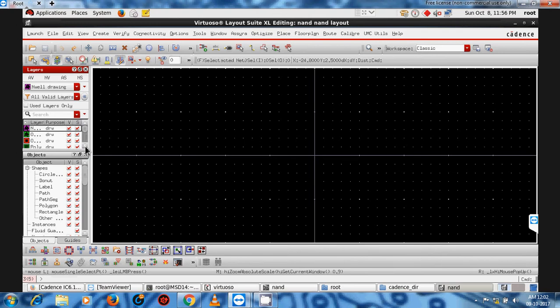Otherwise, if you have Layout XL or Layout L and a schematic with many multipliers, like 10 multipliers or 5 fingers, then layout design is very difficult. So for a schematic using multipliers or fingers, we use Layout GXL, because it has many features which make your layout simple and comfortable.